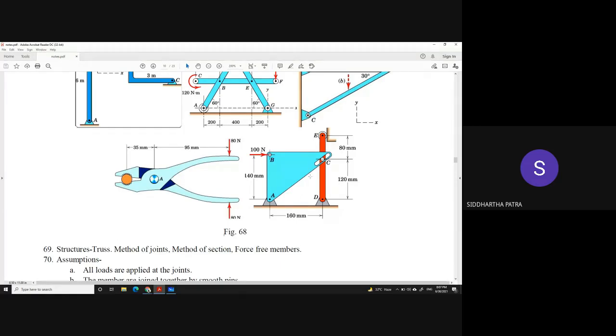It's not even 4. This time it needs 5. So here it is 5. On the picture above it, it is 4. And on the picture left to it, it is 3. So it would depend on how many degrees of freedom the structure had if it were not supported with the ground. So you need to prevent all of those degrees of freedom.